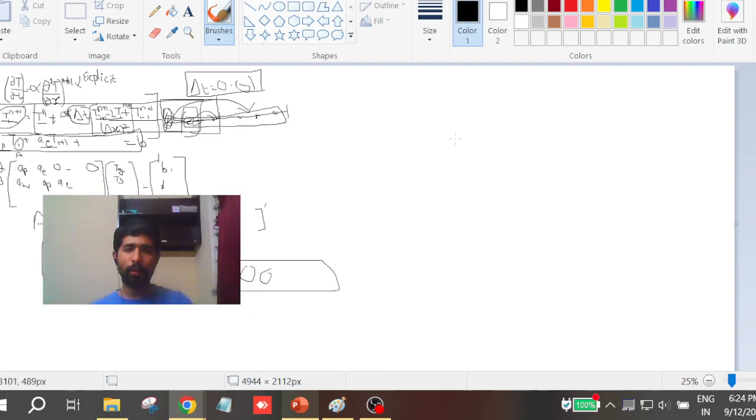There, first you can predict u star and v star using the values of u and v, and p is not required anywhere. U star and v star can be predicted using un and vn. Now to correct this, you already know that we need pn plus 1. To correct the velocity, you need pn plus 1.